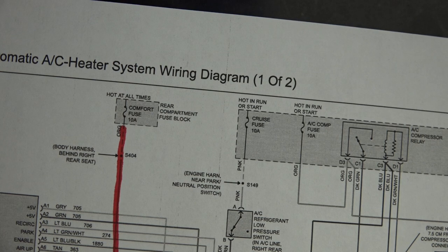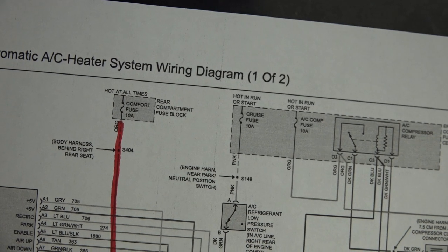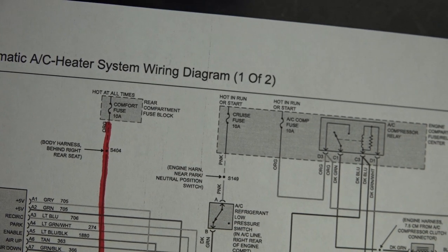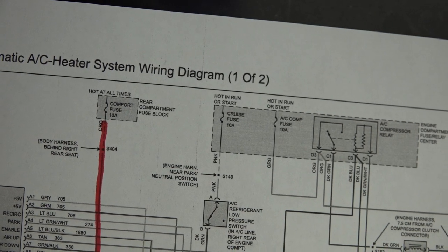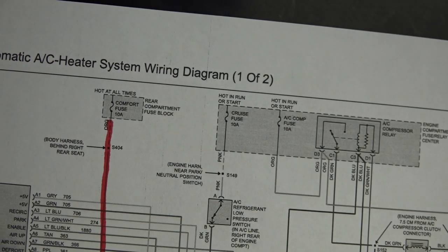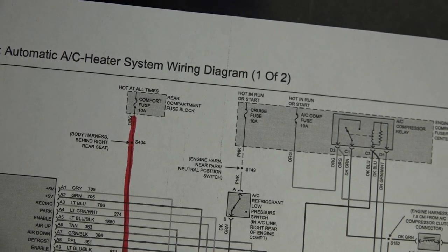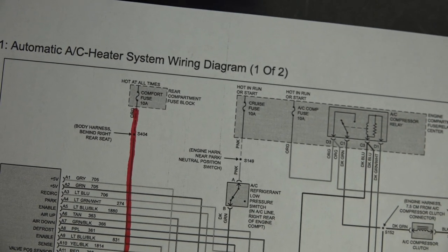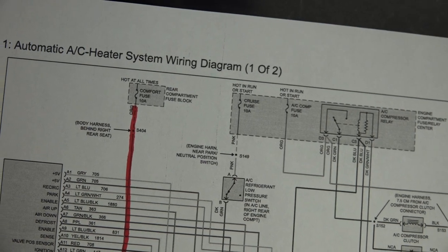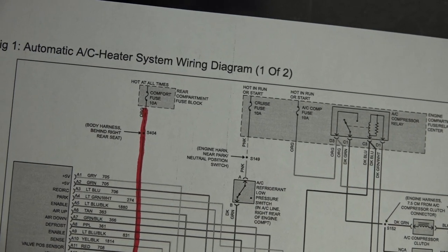So what I want to do is remove that and see if this thing stops pulsing. If it stops pulsing, then that suggests that the programmer is actually controlling this speed up and speed down of the blower motor. So before I do that though, what I want to do is set my scope up.